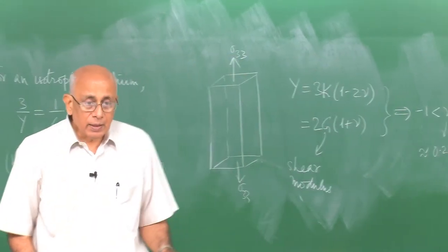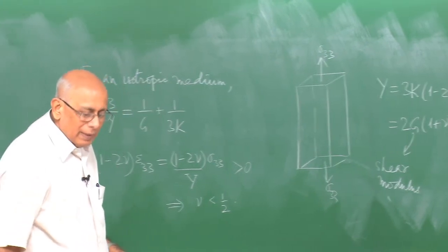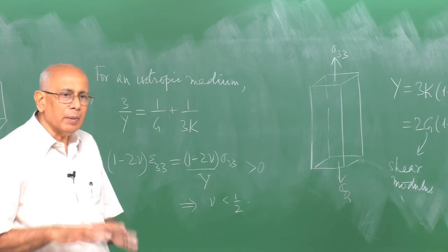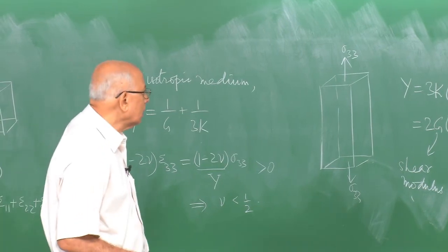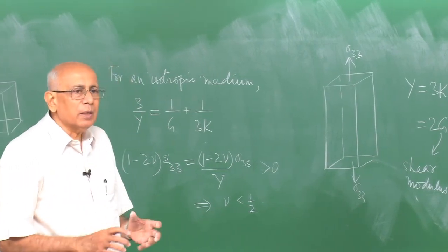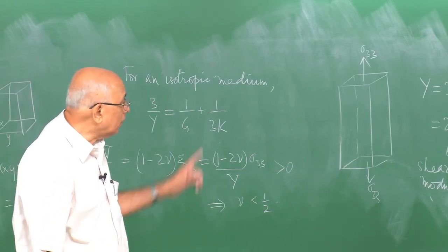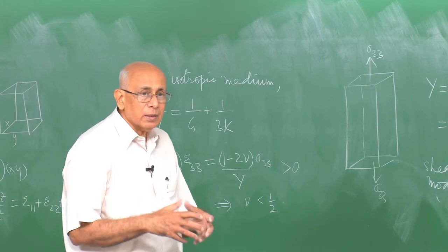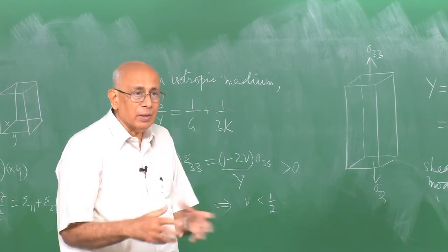Of course there are materials where this is not true, but they may not lie within the purview of linear elasticity. They may be composites, they may be complex materials, and so on. They may have very loose structure, be porous, for instance. You may ask why Poisson's ratio could ever become negative. It can once you have a material that's sufficiently networked in very loose bonds.